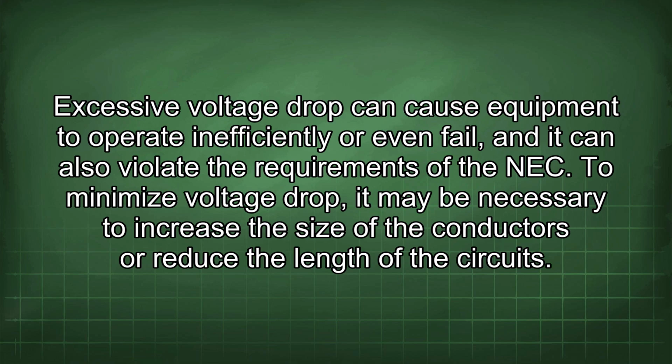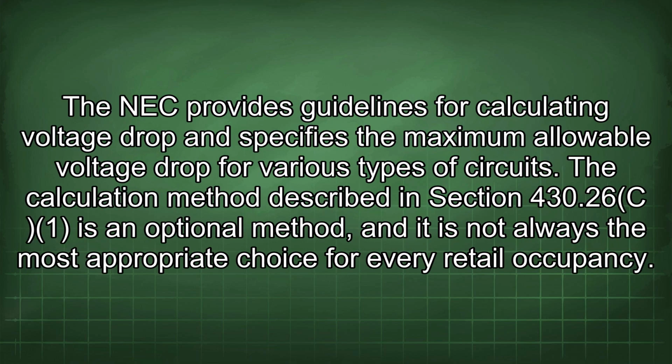To minimize voltage drop, it may be necessary to increase the size of the conductors or reduce the length of the circuits. The NEC provides guidelines for calculating voltage drop and specifies the maximum allowable voltage drop for various types of circuits.